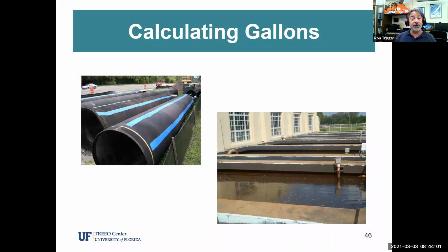We've covered circumference, which is linear feet around something. We've got area, which is the cross-sectional opening of a pipe, or if it's area of a rectangular or square shape, it's the flat surface area. So let's convert these things that we just talked about. Let's start converting these into gallons. So we are going to need the conversion factor of 7.48 gal per cubic foot.